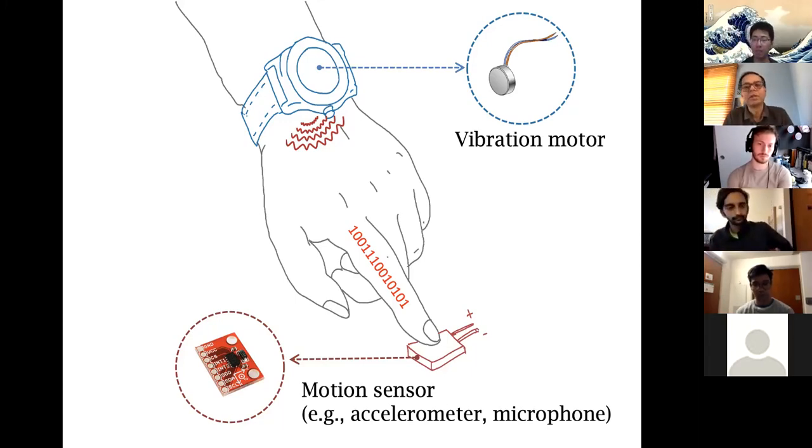Now the question is, why should I do 5 bins? Why not break the 500 hertz into 500 bins? Sure, maybe you can do that, but that means every frequency is now carrying data. Maybe there are problems with that, because if that frequency has some noise and the noise is large, you'll have a bit error.